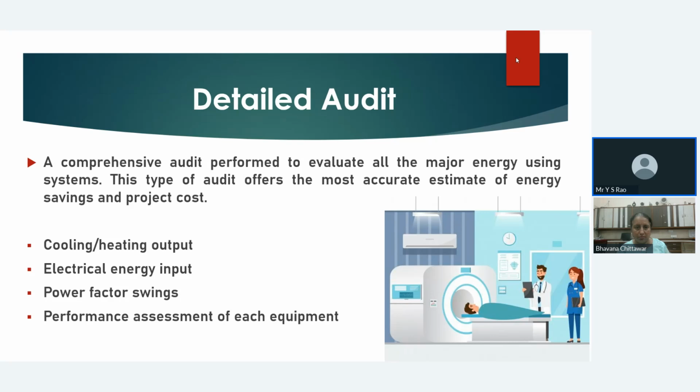Therefore, a detailed audit involves conducting testing and measurements to evaluate the heating and cooling outputs with respect to electrical power inputs. Obviously, the power quality is also checked, and the scope for power factor improvement is also checked, followed by performance assessment.